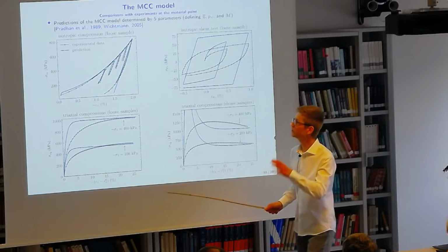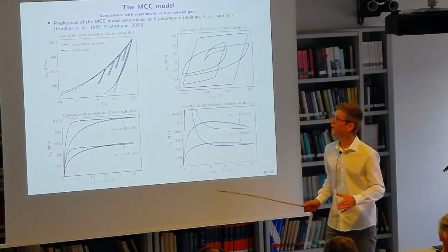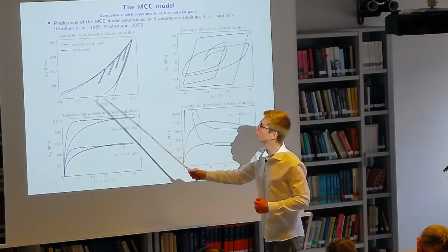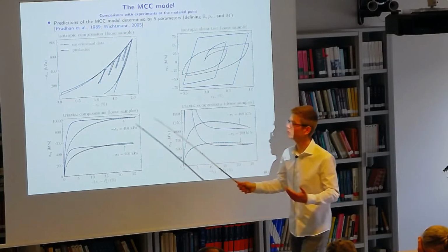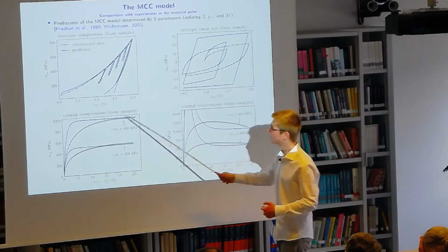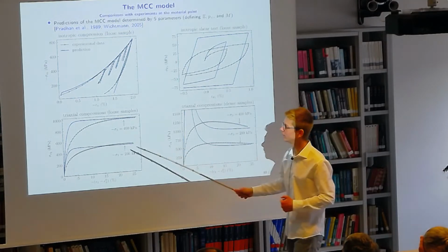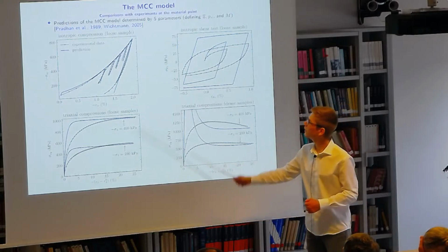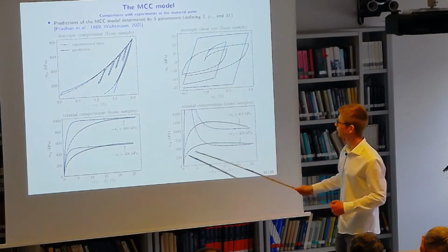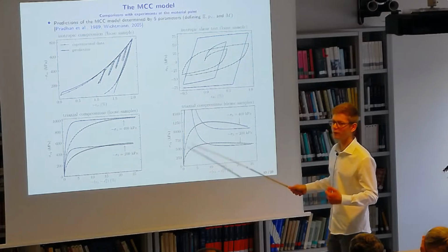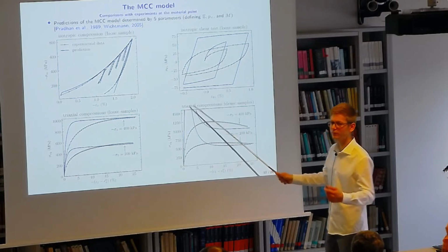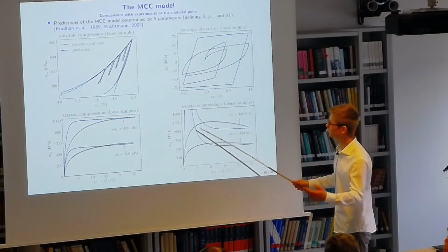When we compare the prediction of this model with experimental data, we can, on the one hand, be satisfied with this prediction for loose granular soil. On isotropic compression, the nonlinearity of the irreversible response can be captured, as well as during triaxial compression, the right ultimate and maximum equivalent stress for different confinement levels sigma 3. However, the model was not designed to predict hysteretic behavior, nor to be realistic with the softening evolution of dense granular soils. In this case, the maximum equivalent stress is much overestimated, and there is a slope which is too acute during the softening regime.